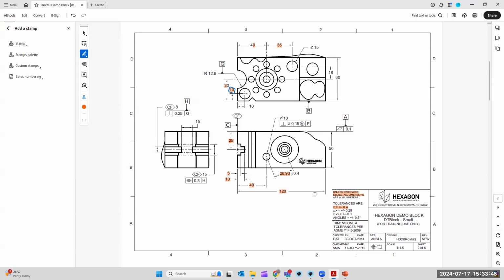Sir, can you repeat the question? So I need to do an alignment now. So I've done my manual alignment. It's just an approximate location of the datums, right? It gives me, okay, here's my machine coordinates. Now here's roughly where they are in the part because I've done a manual alignment. I've always repeated my manual alignment with a DCC alignment, but I've never really discussed with you which alignment you choose to do first.